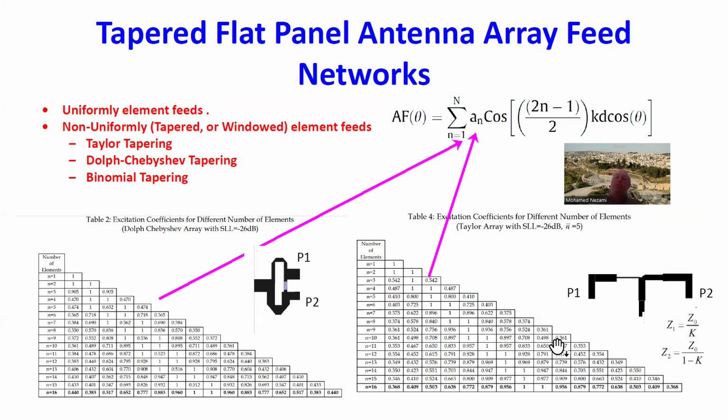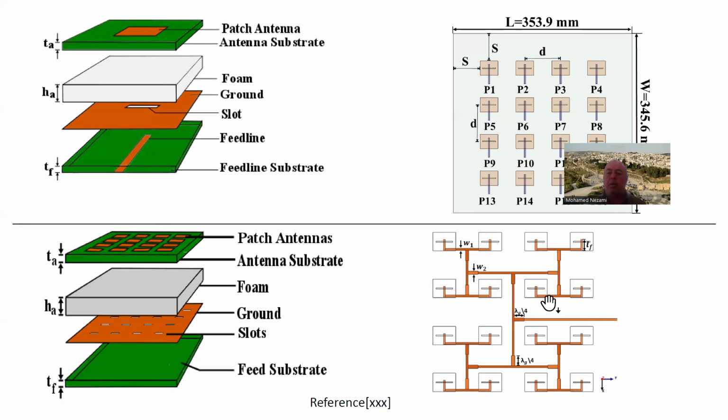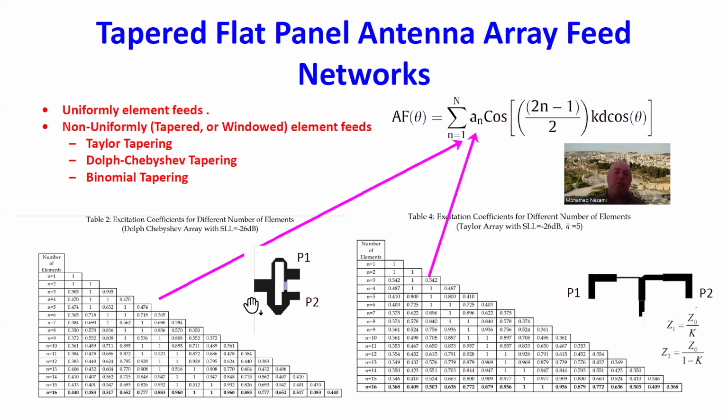And I did show the methodology of how you would obtain these, design this T-junction so that you can actually replicate it. Same thing for Wilkinson divider. Basically, you end up with a Wilkinson divider, which is an unequal power divider. And that's basically what you see in here. You end up with one side of the divider where the impedance is lower than the other side, okay? And the width ratio in here is directly proportional to the power ratio between these two outputs.